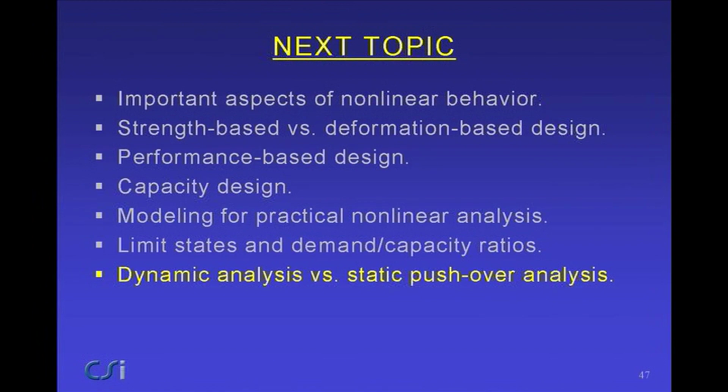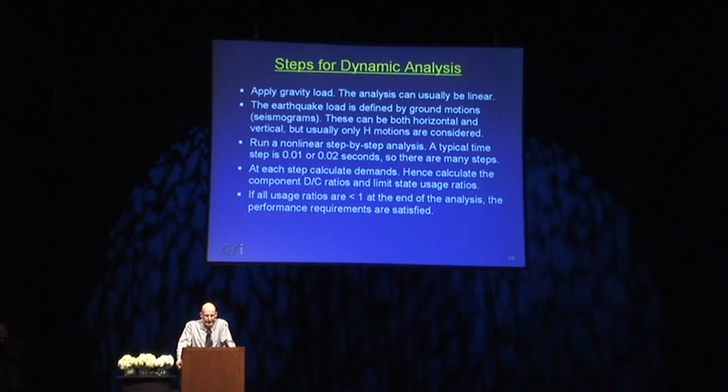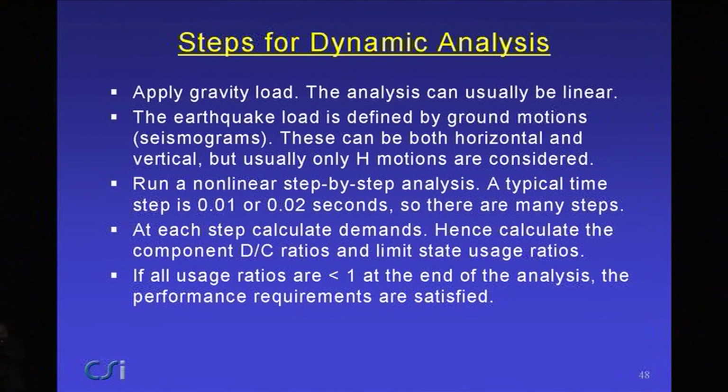Dynamic analysis first, the steps are as follows. Apply the gravity load first. Usually the analysis can be linear. Not always, but usually. The earthquake load is defined by ground motion, seismograms or accelerograms. Typically you'll have both horizontal and vertical seismograms. Usually you'll only consider the horizontal motions. You can consider vertical motions in Perform 3D if you like, but it opens up all sorts of cans of worms, and usually we don't.